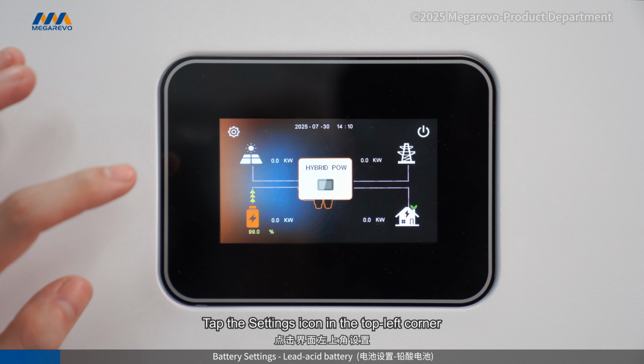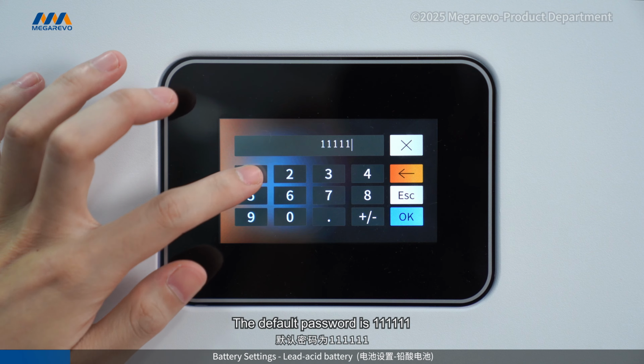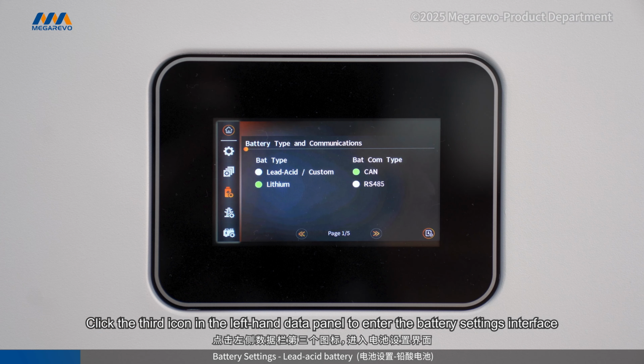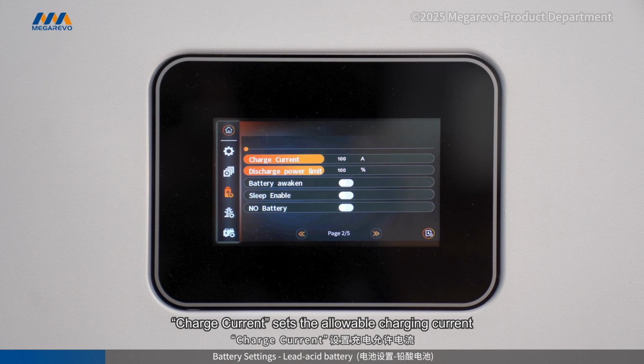Tap the settings icon in the top left corner, enter the password. The default password is 11111. Click the third icon in the left-hand data panel to enter the battery settings interface. Battery type supports selection: lithium battery, lead-acid battery. Charge current sets the allowable charging current.